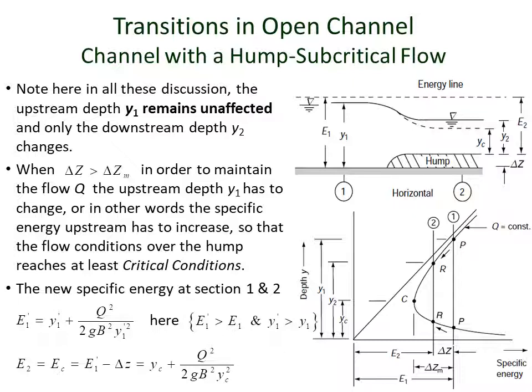Now, to what extent should the upstream flow depth increase? We can imagine from the diagram that y1 has to increase to such an extent that the downstream flow condition at section 2 should at least reach the critical condition.